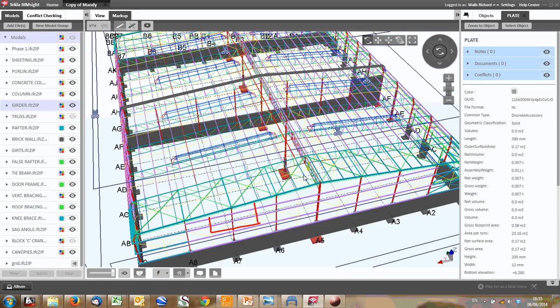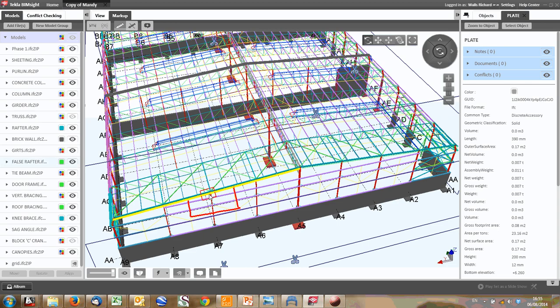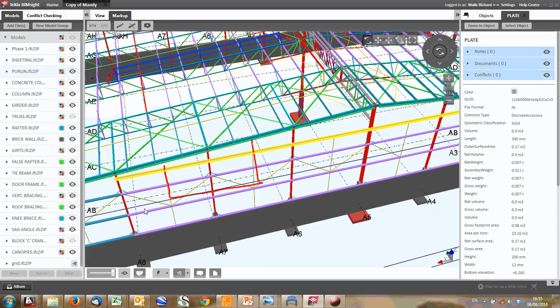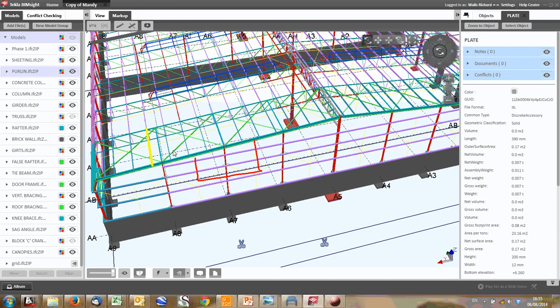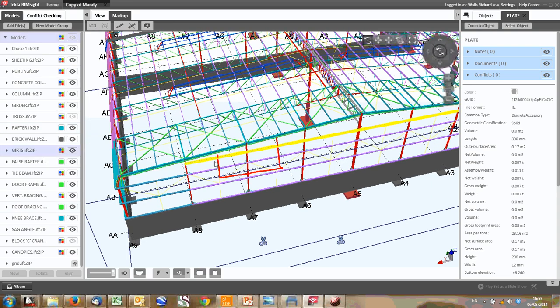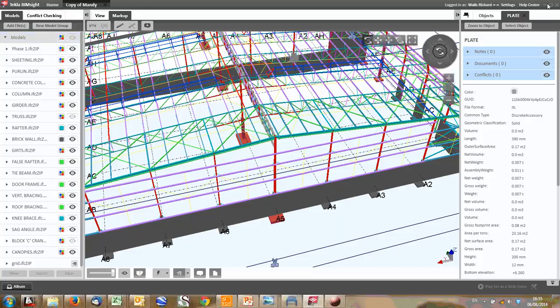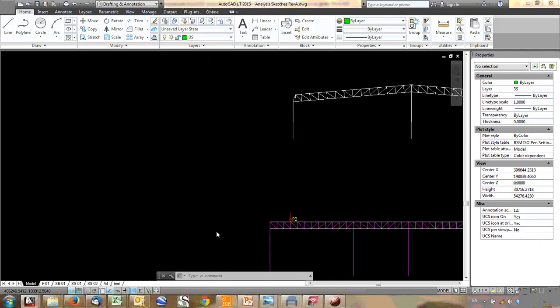If this brace bay is carrying the other face as well, you need to add that face to this load. But you'll see why just now we actually have two braced bays for the gable, but only one for the trusses, right? So this load now will come into this brace vertical, this horizontal brace all the way along the top. And there we are. We can quickly calculate our loads and then design for it. We can design this all the way along, and we'll get a reaction. From this, we get a reaction, which we then can apply to our girder.